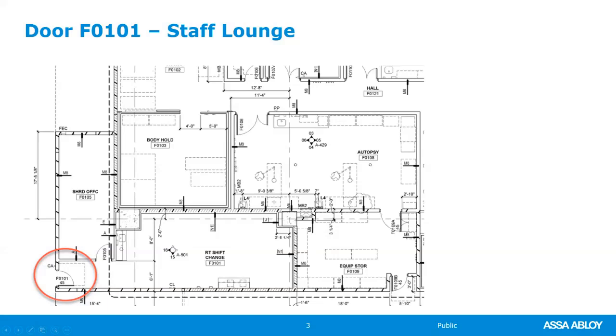Any room that you can normally lock with a key, classrooms, storage rooms, offices, any type of room that you can normally lock with a mechanical function lock set can be fail secure if you need to make it access control. So this is just a mortise lock that has wires in it. Fail secure means that when the power is out, I need a key to get into this space. I can always get out. I have free egress. Because this is a mortise lock that allows free egress, this can be fail secure. Let's take a look at the hardware set.